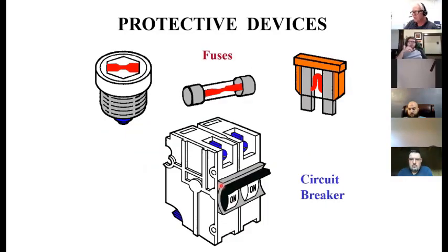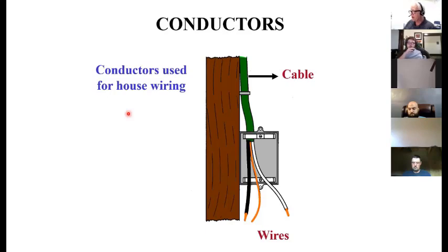They're just charging you for the supply. These are some simple devices that you would see in most circuit protected devices. We said last week, they're not there to protect you, they're there to protect wires. They're essentially fire protection devices. If you try to put too much current through a wire than what it was designed for, the friction that's created is so great that the heat generated can melt off insulation, and that might cause a short circuit that has even more current flowing, and it can start fires. And then conductors: we've talked a little bit about circuit board traces, cables, wires. Anything that's carrying the current to the load is a conductor.